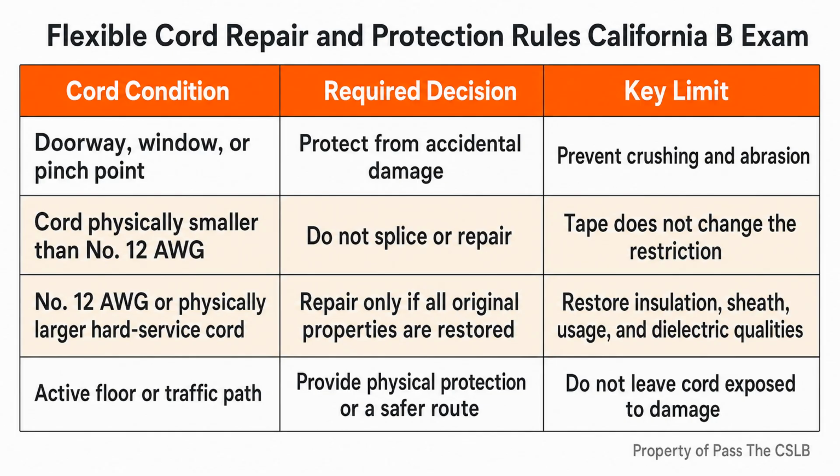A ladder, stack of drywall, pipe bundle, tool cart, or scrap pile occupying the required working space creates an access problem and can interfere with operation or emergency de-energization. This is one of the easiest hazards to create because the panel space often looks like unused wall area. It is not unused. It is reserved work access.